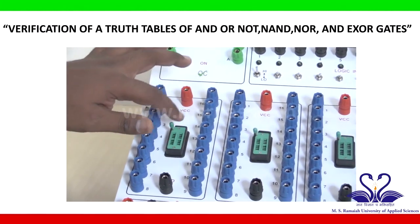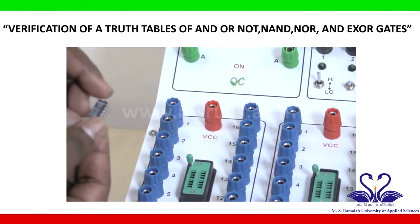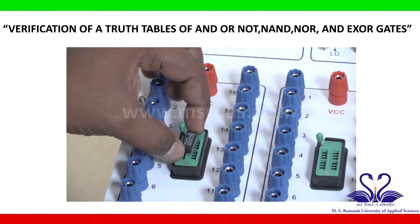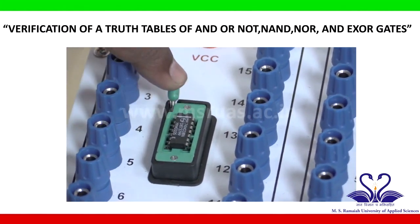So this is the IC mounter. There is a notch. This is pin number 1. So I will mount it on this slot such that the pin number 1 should go in the first slot. Then I will lock it.